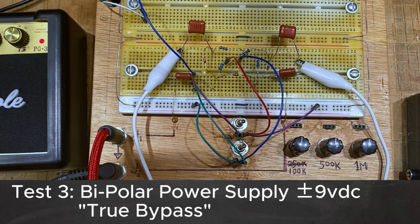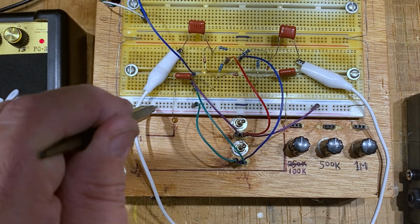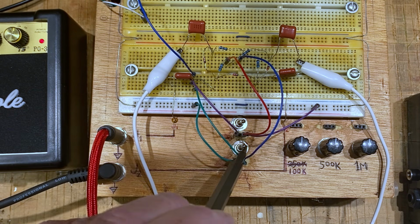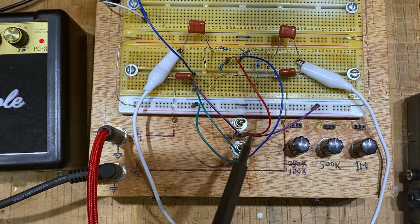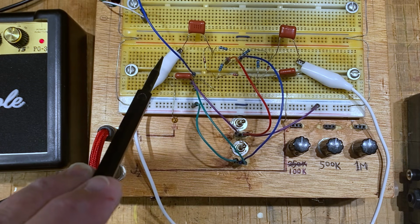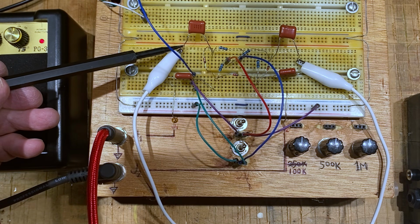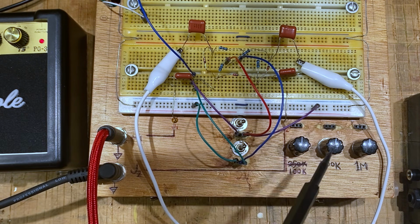All right, I have rejiggered this. I now have a bipolar power supply on here. So instead of having these toggles go back and forth from positive 9 volts to ground, now they're toggling between plus 9 volts and minus 9 volts. So I have 18 volts difference between the power rails. And to make matters more easy for testing, I have the effects send and the effects receive. I just have this single alligator clip running around there.